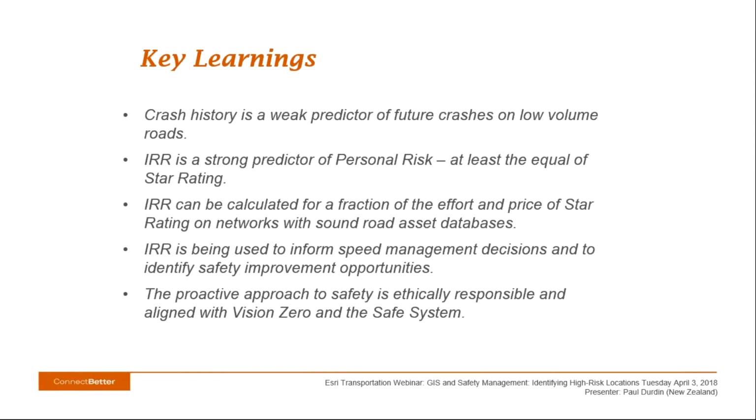So the key learnings in relation to the rural roads are that crash history is a weak predictor of future crashes on low volume rural roads. IRR, by contrast, is a strong predictor of personal risk and at least the equal of star rating. IRR can be calculated for a fraction of the effort and the cost of star rating on networks with sound road asset databases. It's being used to inform speed management decisions and to identify safety improvement opportunities in New Zealand. And the proactive approach to safety is ethically responsible and aligned with Vision Zero and the safe system.